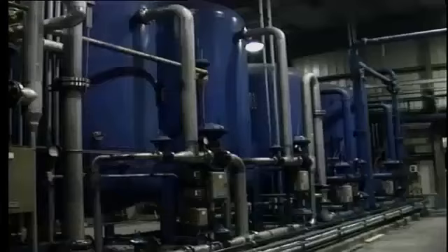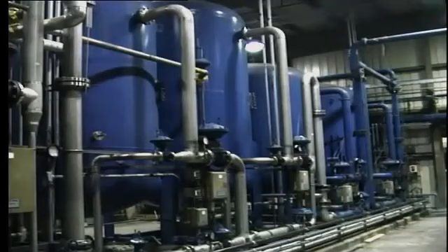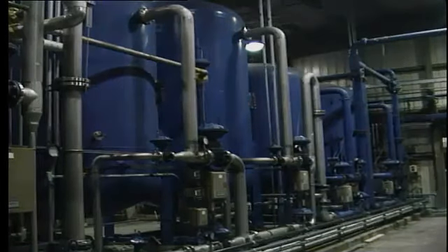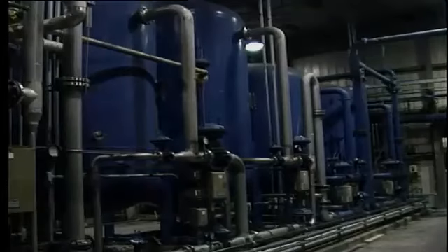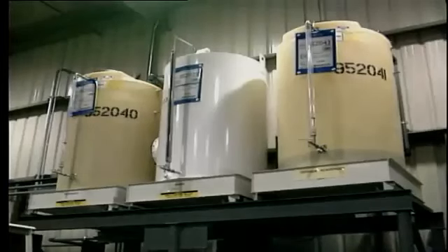When we're speaking of water control here, we're referring not to the water level control, but rather to the quality of water which is contained in the boiler. We already know that a special water treatment plant, including demineralizers and other equipment, is installed in order to ensure that water which is fed into the boiler is super pure. Additionally, certain chemicals are injected into the boiler drum to further control the chemical condition of the boiler water.